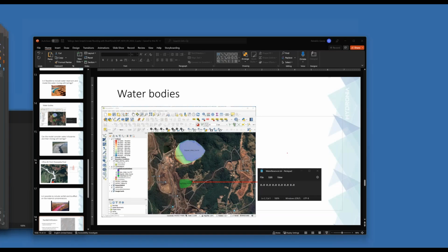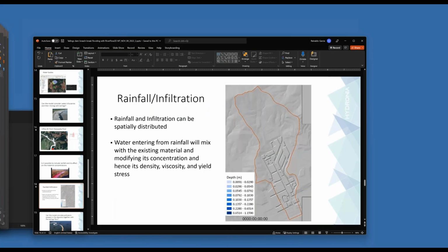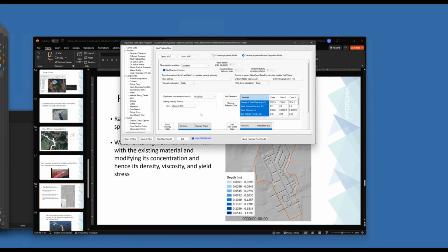So in the model data, depending on the equations that you select from here, for instance, then you have other factors that you may play with, like settling velocity factor. So the settling velocity, the lower the factor, the less sedimentation will occur. So you can use that.